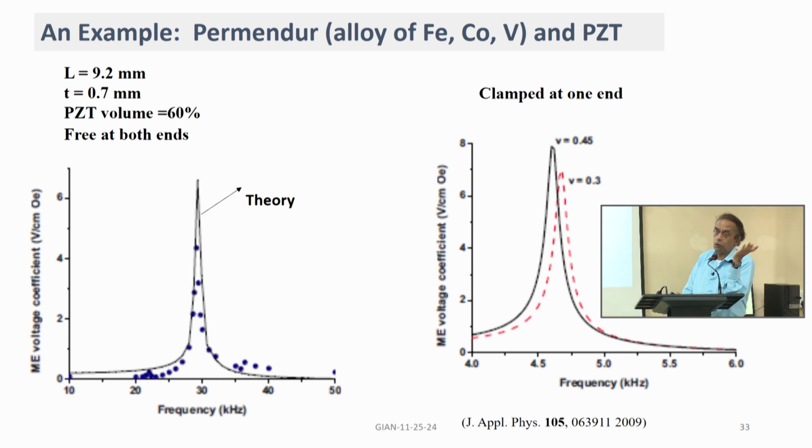Previously, when I showed the low frequency response, at low frequency, the voltage coefficient is maybe around 300 or 400 millivolts per centimeter Oersted. This is practically 10 times that or 20 times. Okay. So there is a significant enhancement in the voltage coefficient under resonance conditions.